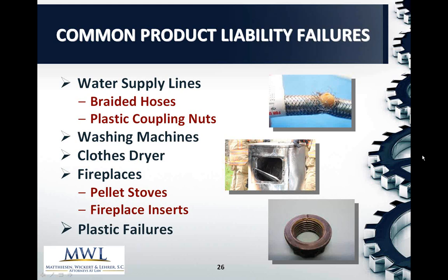In plastic failures, I kind of touched on that. Why they fail. The threaded coupling nuts. A lot of times it's the stresses involved. It really needs to be the correct type of plastic. It needs to be designed correctly. A lot of times the threads are too sharp, and that adds increased stress. The plastic is going to fail over time. It's not going to be an immediate failure.